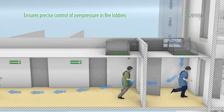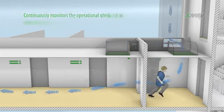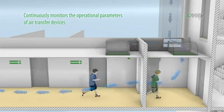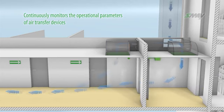It ensures precise control of overpressure in fire lobbies and continuously monitors the operational parameters of air transfer devices, by which acceptance tests and periodic commissioning tests of pressure differential systems for buildings are completed faster.